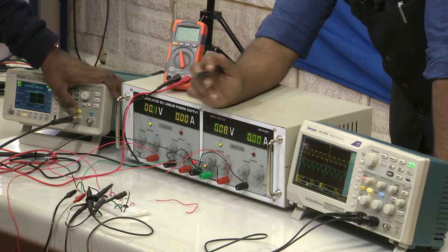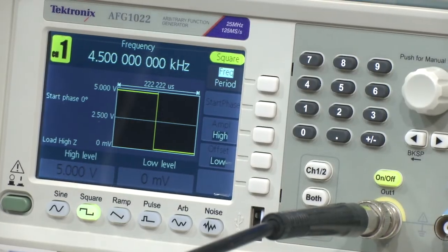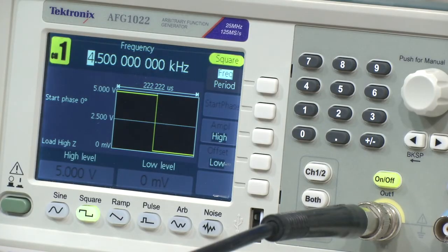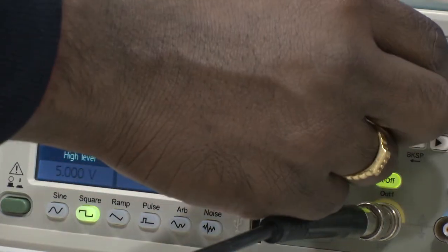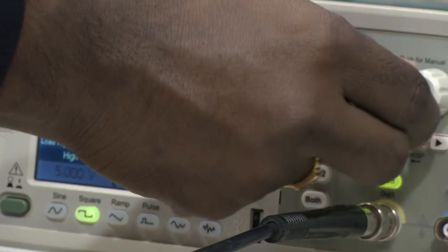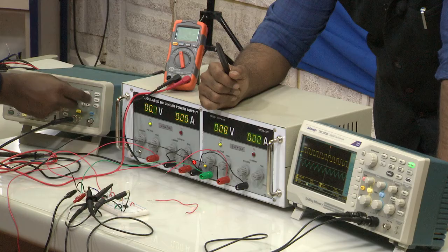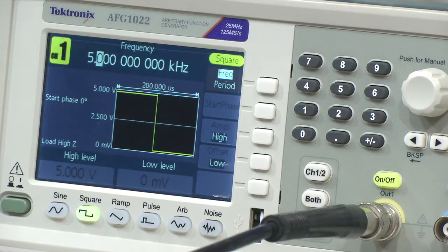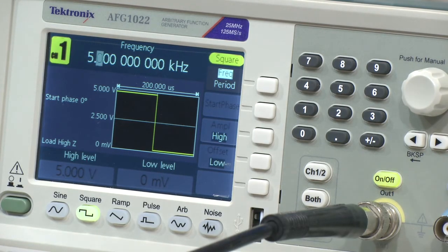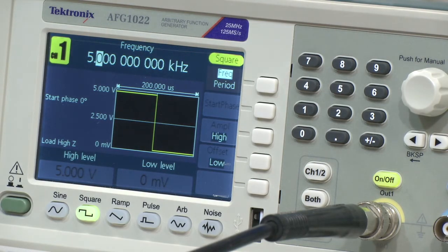Alright. So, let us see the function generator and what he is applying right now. If you see, he has given a square wave at 5 kilohertz, and the peak to peak voltage is 5 volts. Again, you should immediately be able to see that when I say peak to peak voltage, it is from 0 millivolt to 5 volt on the y axis, and the frequency is 5 kilohertz.